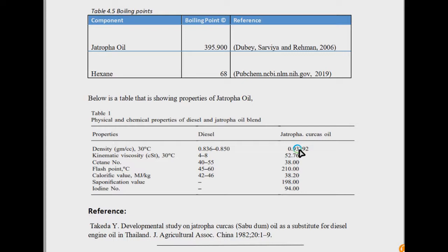The weight of exhausted seed cake can be very simply calculated from the material balance: total seed minus the total oil extracted. It will be the exhausted seed cake amount. But during the heat transfer, a heat transfer coefficient is involved with its area that is providing the heat. For example, if we are using a coil of copper with a boiling water stream inside, its coefficient is assumed, from the literature references, to be near 670 watt per meter square Kelvin.